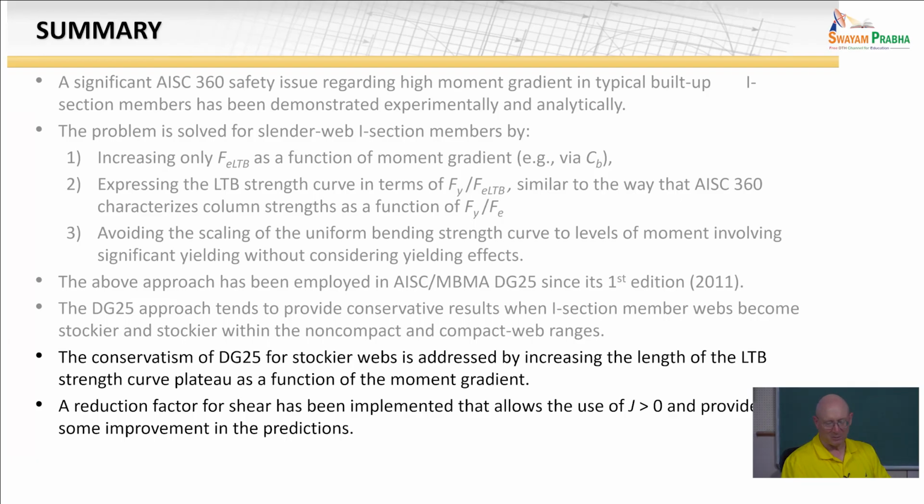And so that's, I think, a good change, in terms of we can base our calculations all uniformly on the mechanics, using all the terms, both the St. Venant torsion contribution as well as the warping rigidity contribution to the lateral torsional buckling strength. In all cases, then, we take a reduction off of that.